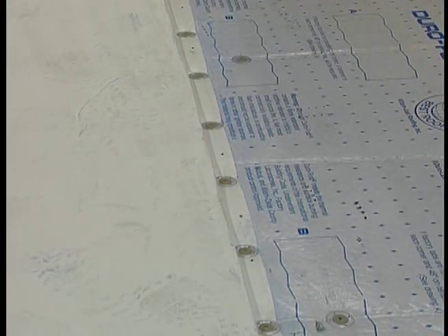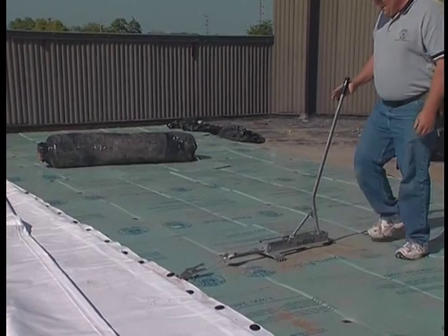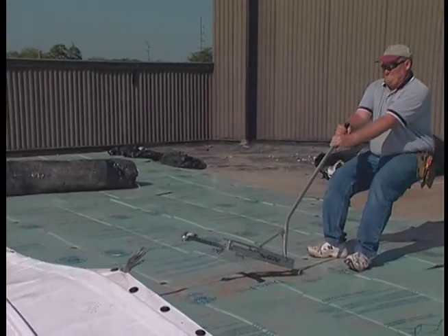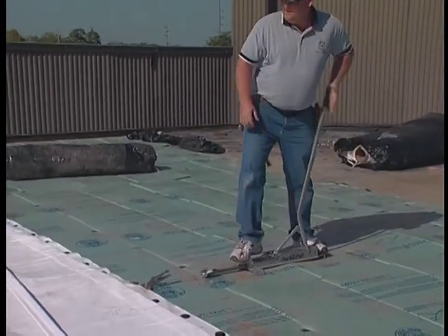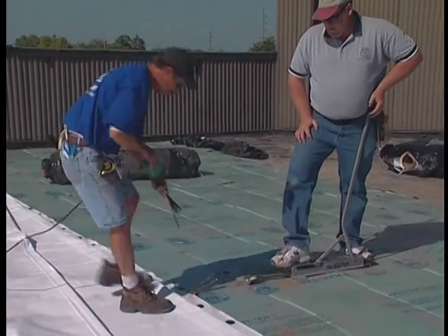When the first tab has been fastened, unfold the Duro-Last membrane covering the first row of fasteners. From the installed sheet side, fold the unattached material toward the tab to be installed, exposing the single layer of membrane covering the roof. This will allow you to assure that there are no wrinkles in the sheet when it is fastened down. Position the grip pole in the center of the tab to be fastened and pull at a right angle to the tab, removing the wrinkles. Install a plate and fastener at this point.